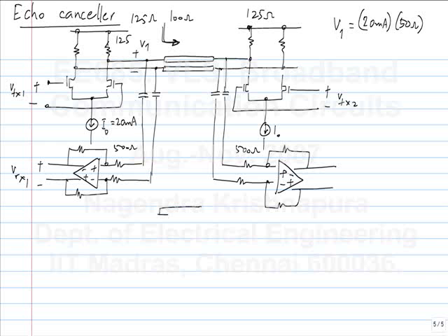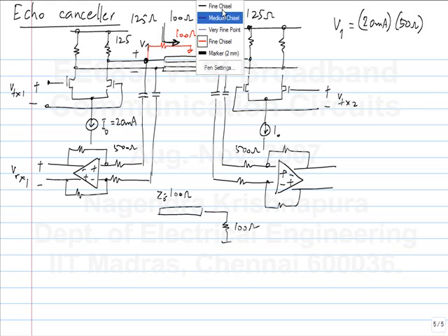So the situation you have is a transmission line terminated by 100 ohms and the impedance is 100 ohms. So it's like connecting 100 ohms from here to ground. Essentially I have 100 ohms to ground here. Small signal wise, or rather incremental signal wise, it is ground.